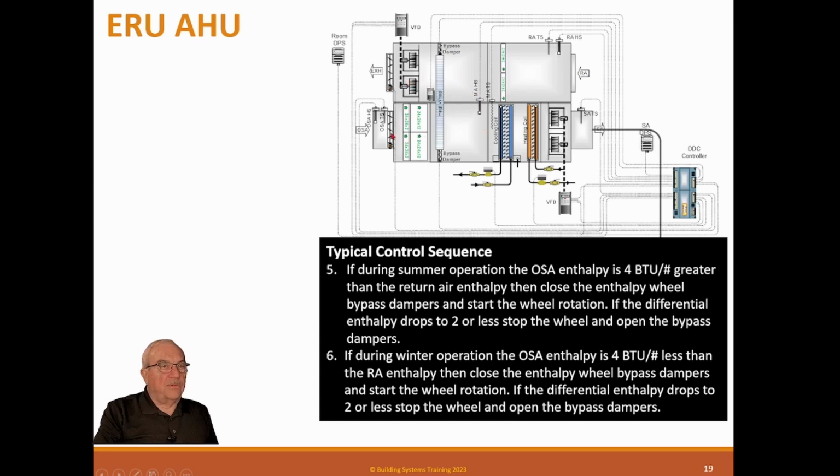And the reason for it is if this one, let's say this one coming from space, has some lint on it, gets through these filters, and it impinges on this wheel. If this one went the same way, then it would just try to push that lint further in the wheel. But since it's going this way, it'll actually push that lint off. So that's really important because these can get impacted, and if they do, there's somewhat of a problem.